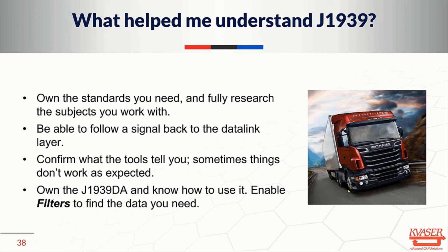Okay, be able to follow a signal all the way back to the data link layer, like I've shown you how to do here. Confirm that the tools that you're working with are reporting the correct data if there's any doubt. I've found a lot of mistakes in tools. You can spin your wheels for hours that way.